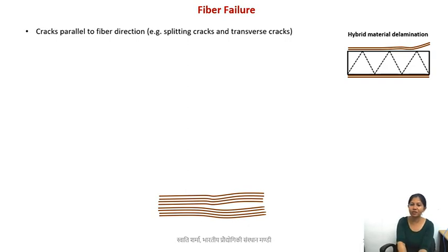So in the case of fibers, we are first making the fibers, then we are braiding the fibers, laying them in certain directions, and ensuring that they are braided in a certain direction, that they have either parallel or perpendicular structures. Then these sheets we take and we place them one on top of another, again at well-defined angles, and we infuse the resin between them.